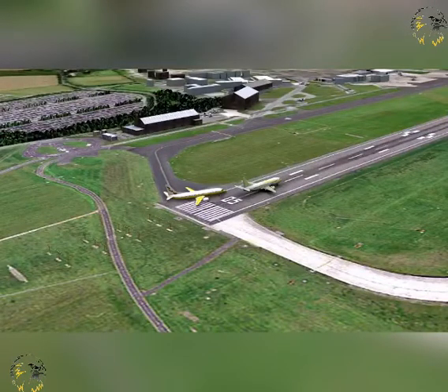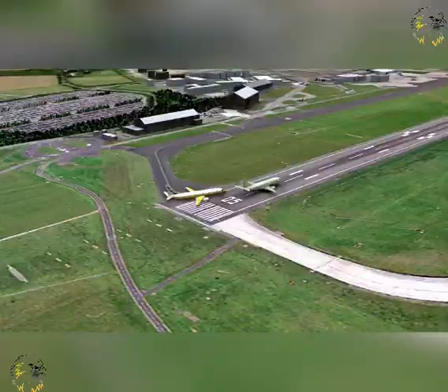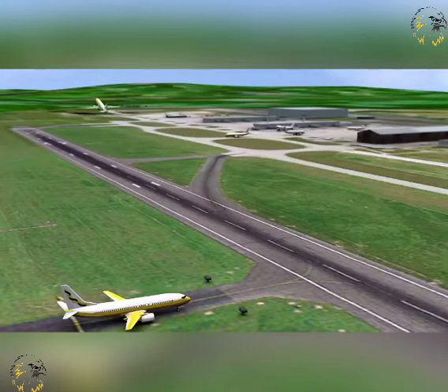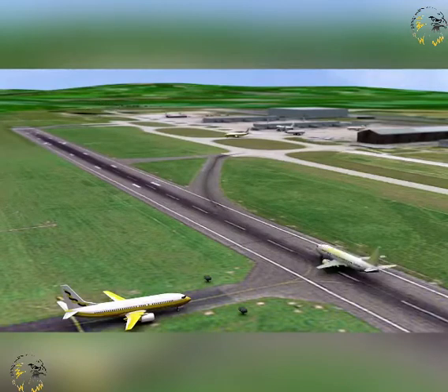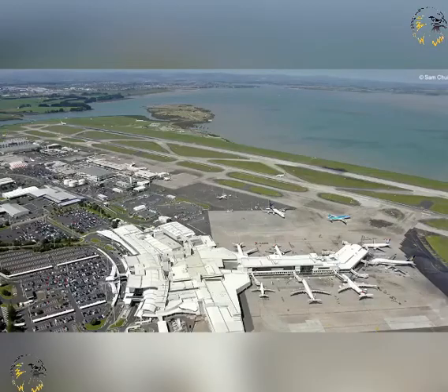Consideration must also be given to the places on taxiways where aircraft hold, prior to entering a runway for takeoff, for example. The large mass of an aeroplane may also interfere with ILS or MLS systems if parked in front of them, or be a significant obstacle to landing aircraft if parked too close to the threshold. In general terms, however, taxiways should, according to Annex 14 of the ICAO regulation, provide safe and expeditious surface movement of traffic. A major limitation to an aerodrome would be the capacity of its taxiways to accommodate different sizes of aircraft.